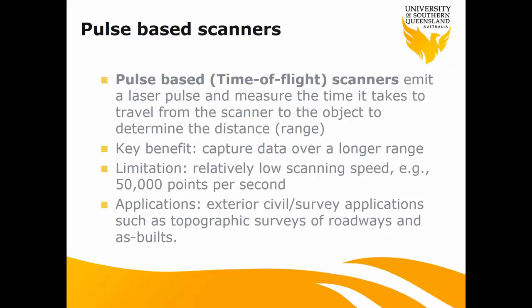The drawback is a relatively low scanning speed, probably only around 50,000 points per second. So it's mainly used for environmental applications. In the survey area, in open cut mining and industrial settings, that's very good because we need a long range.